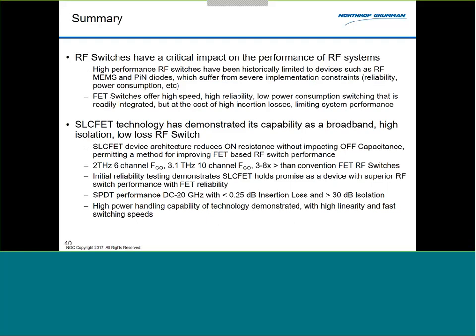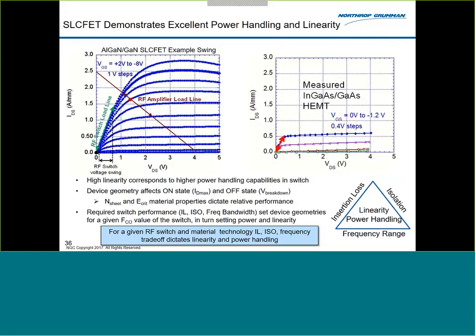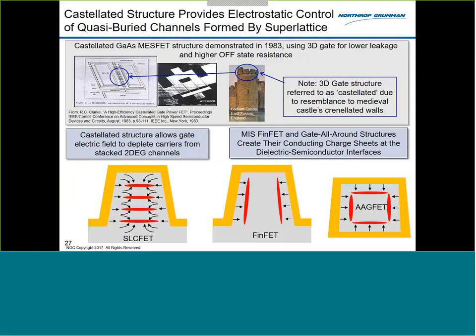One of the interesting things about this is that I showed you this nice structure. We have the picture of the SlickFET on the left, and as I mentioned, it's a MISFET structure where we have these essentially buried channels of the current connection. But there's also a parasitic MOS device here, which I don't show at all, because we have our gate, the insulator, and that sidewall.